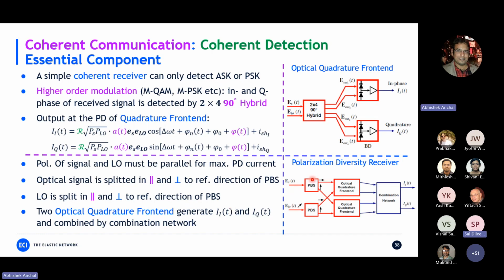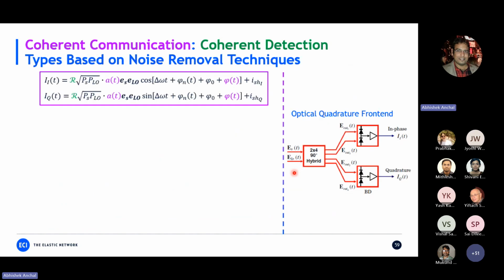Yes. And not only that, you remember that we have two different polarizations. We transmit DP, dual polarization signals. So there also we use a polarization diversity receiver in order to combine, because your information is in 90-degree different polarizations, right? In all our Acacia modules, we do not transmit just QPSK, we transmit dual polarization QPSK. So these two orthogonal polarizations also use this setup in order to combine the bits or information in polarization to get detected. We can see that later on in the slides.